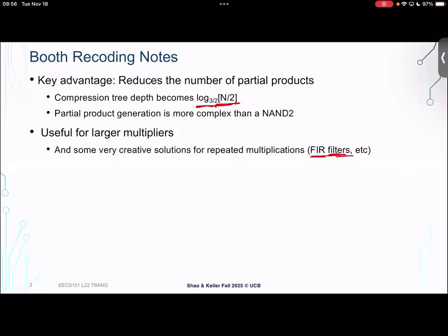Yes, good, very good question. So radix 8 Booth encoding would be looking at 3 bits at a time instead of 2. You can do it. People have done it. You can't just get away with A and 2A anymore. So you do need to now generate 3A in order to make that work, that hard multiple. And the number of partial products has just gone down from n over 2 to n over 3, right? If you're looking at 3 bits at a time.